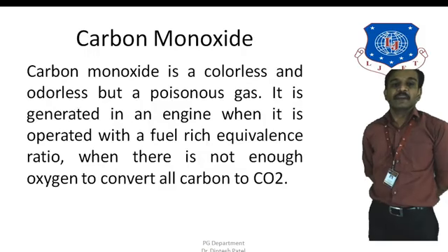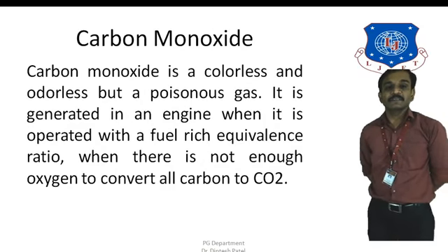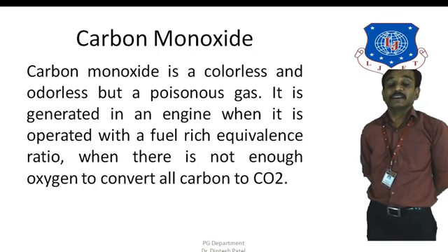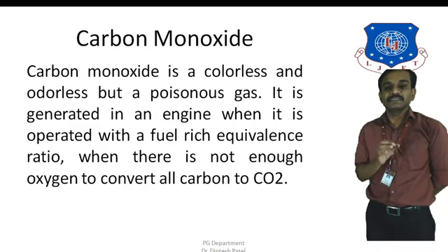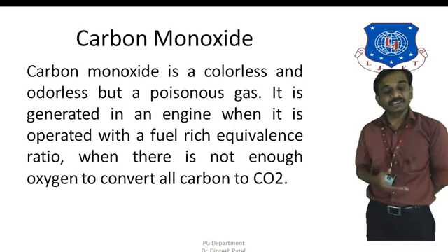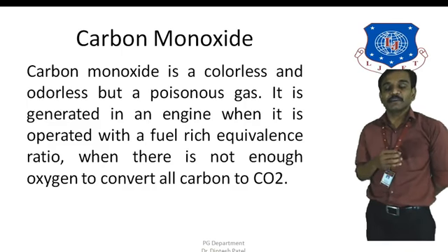Second one is carbon monoxide. Now carbon monoxide is a poisonous gas. It is colorless and odorless, but it is highly poisonous, and it is mostly created during the combustion of a rich mixture. That means when the engine is operated in initial conditions, or when the engine is operated with the highest amount of load, or when you suddenly open the throttle.